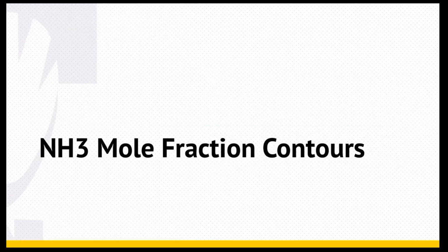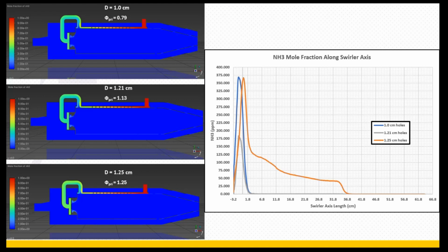And now going on to the ammonia mole fractions. So all these pictures look very similar, so you have to rely on the chart to see the actual differences. You got your pure ammonia fuel that comes in from that vertical pipe and goes down the length of the cracking channel. You see this composition changes, with some sharp gradients around where it has to go vertical. And that's due to all the molecular diffusion and the velocity recirculation going on as the flow's turning. But then after enough pipe length, everything equalizes out, and then it injects into the burner.